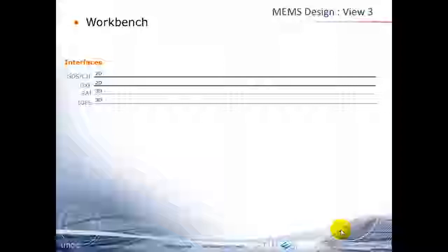And if you look at the interfaces in the modeling part, you have 2D modeling and you have 3D modeling. We have to live with the GDS language, which is standard because we have to make the masks. But in the mechanical world, there exists historically the Drawing Exchange Format from AutoCAD, and most programs have some kind of import for that. So that's an important one which you should put your attention to. There are also 3D interface languages, and one of them is the IGES format.